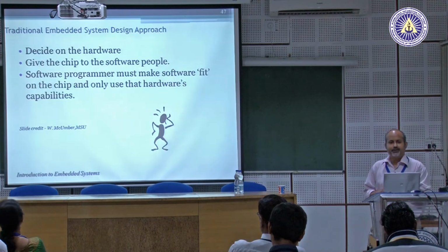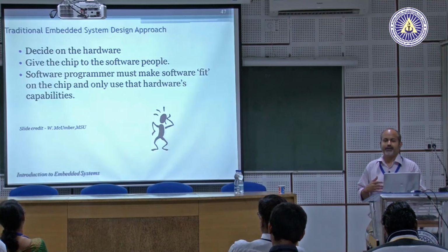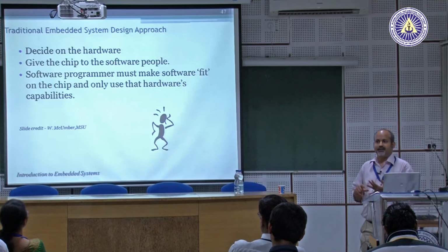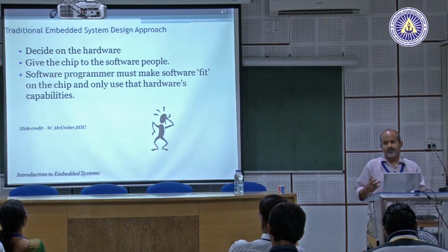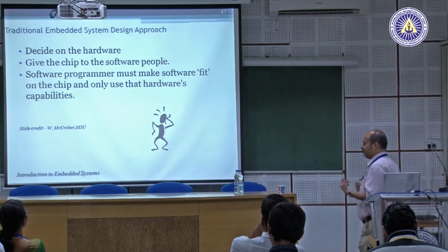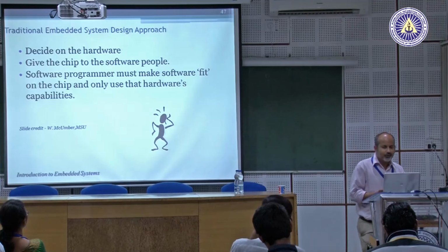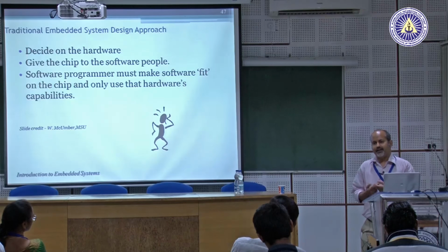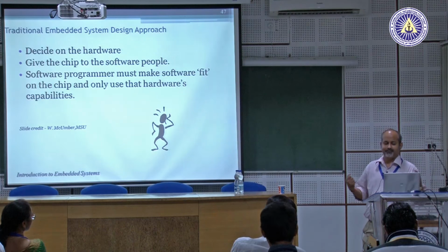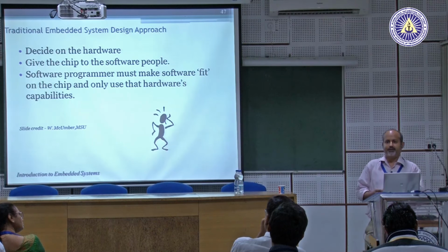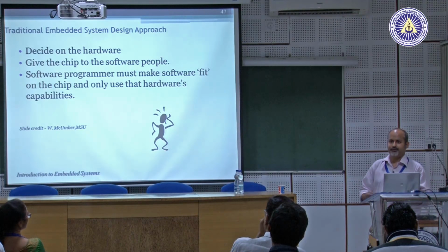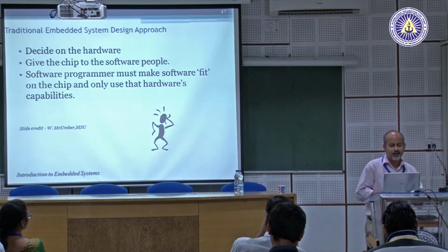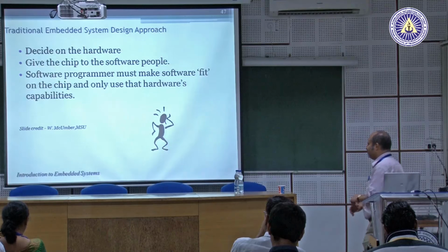Normally you decide on the hardware based on other considerations, including availability, cost, and power budget, and things like that. And also your data path requirement. If your data is only just some few control, then you may want a 4-bit microcontroller. If your data is also actual data with voice data or video data, you may want a wider data path, like 32-bit, 64-bit data path. So the processor choice is often based on all these considerations, which is not following this requirements to implementation framework.